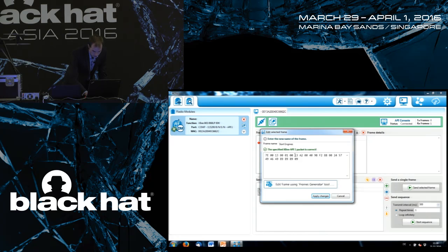So the first packet here that we will send is the command start engines. And the text that is highlighted right now is the address of the chip of the UAV, because we obtained the address before by extracting the sender's addresses from the acknowledgement of the broadcast packet, right? So we actually know the address, and therefore it's inserted here. And this here, that's the payload we are sending to the chip.